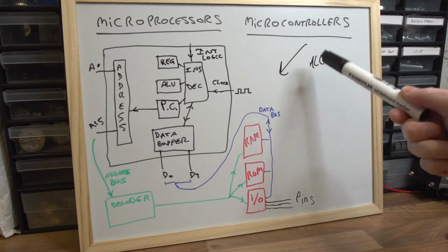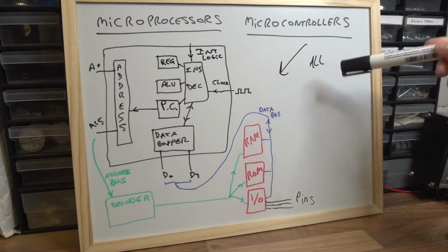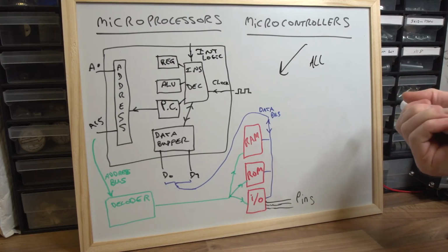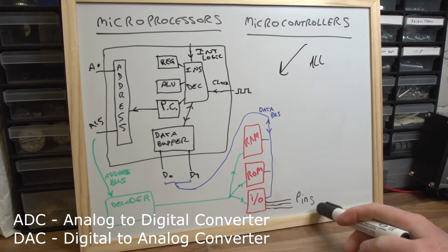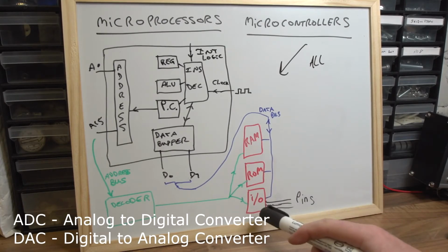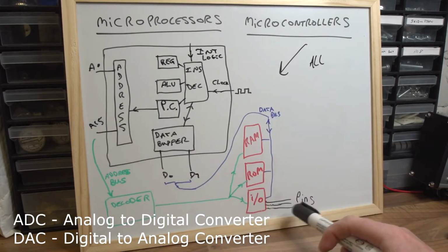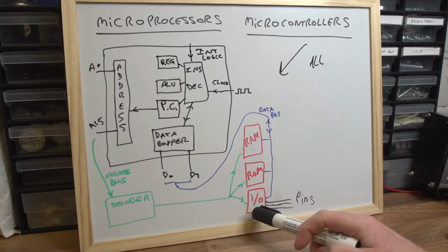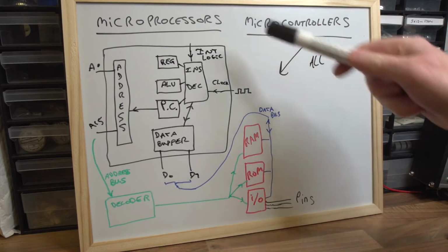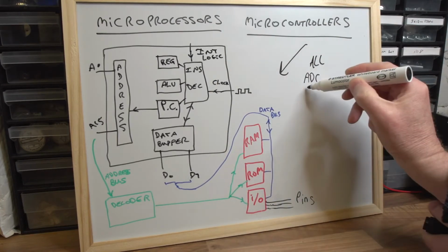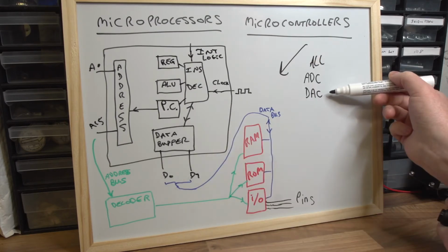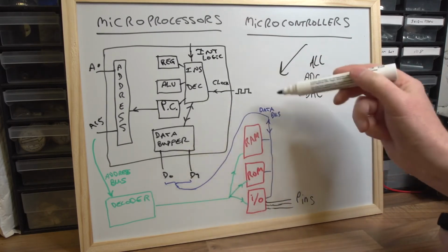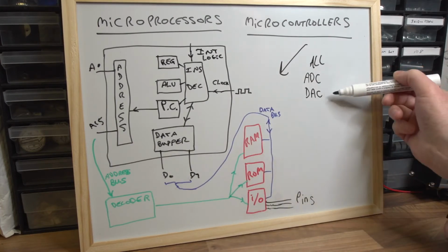It's all built in and more, because these days with microcontrollers you also have ADCs, analog digital converters, you have DACs, digital analog converters, which is all part of your I/O really. But it works with analog voltages as well. It's not just digital signals like we had on the microprocessor circuit with a basic TTL or whatever it is, 5-volt in-out signals. Microcontrollers have ADCs, DACs, that's analog to digital converter, taking analog signals in and converting them to a digital representation, or digital to analog converter the other way, sending a digital representation of a signal out through an analog pin. So that gives you real voltages.